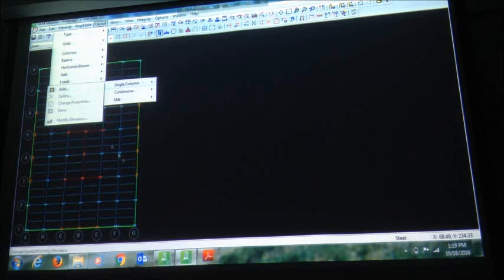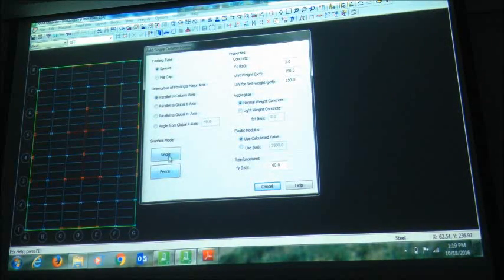Single column. For those cyan columns, I will add single column foundation. So, go layout, foundation, single, add, and I'm going to use the default. Either you can use a single, it will place a column there, or if you right click and say fence, look, I'm doing all the blue ones, not the red ones.